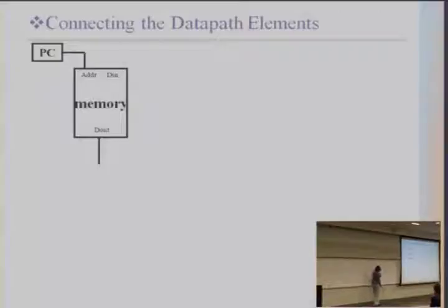So I'm adding Ry and Rz and storing it in Rx. So the PC will tell me which address in memory I need to read this instruction from. Once I do that, the memory stores in the instruction register basically this whole instruction. And in reality, it will be a bunch of zeros and ones.